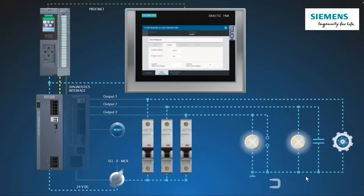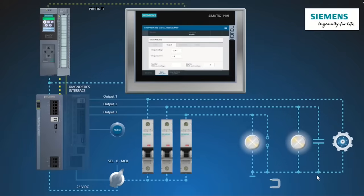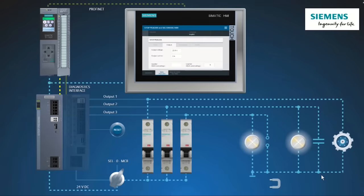And then in the first step, I will show you the overload behavior from the power supply with the miniature circuit breakers. And therefore, I will go here to the right place in the video, where there is a little motor, this little wheel, and now you see in the normal operation mode the motor will take around 2 amps from the power supply, of course. And now I will block this motor, and you will see that the output current from the power supply will increase from 2 to 3 amps.